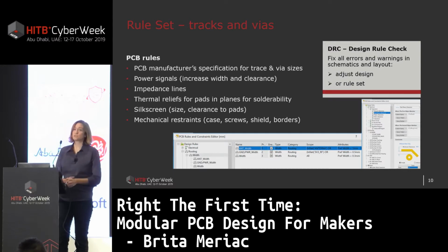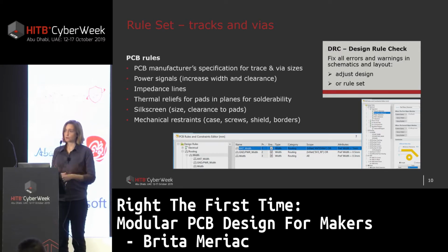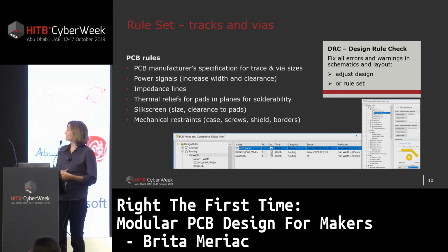The specifications for via sizes depend directly on your choice of layers. It will also be specified by the PCB manufacturer. It gives you guides on via sizes, on track widths and clearances. And the list of possible rule sets in your layout software is actually pretty long and might be confusing. But I think there are 5 points worth a closer look.